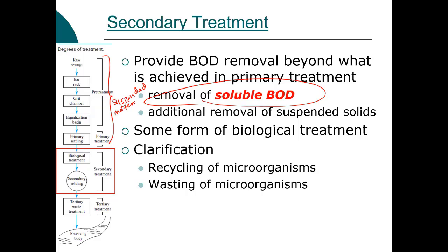So it's focused on removing that large material, the twigs, the rags, the toys that got thrown down the toilet and flushed down the toilet. In the bar rack, it is focused on removing inorganic material, in the grit chamber, and then on suspended solids in the primary clarifier.